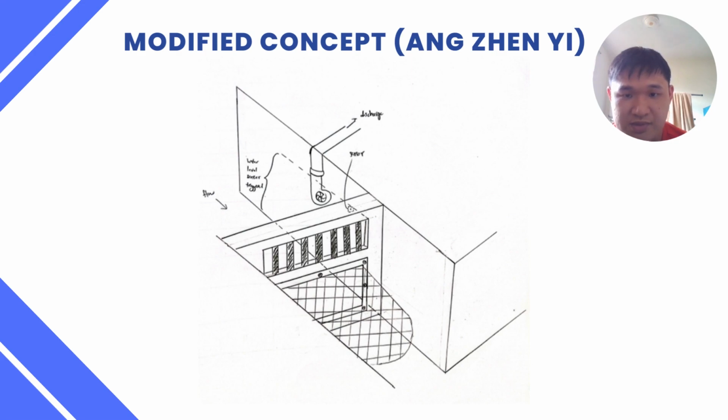Additionally, the water pump has been moved to a position before the physical barrier because the water level will rise faster upstream of the physical barrier when the net is full of trash. This can cause the water flow through the net to slow down and in turn slow the rate at which water is discharged downstream of the physical barrier. By relocating the water pump to a position before the physical barrier, the system is able to quickly and efficiently remove excess water from the system, even when the net is full of trash.